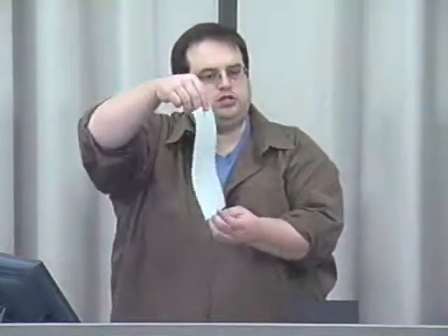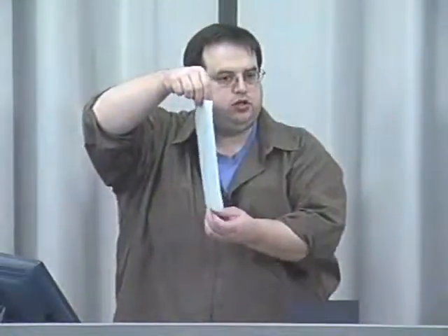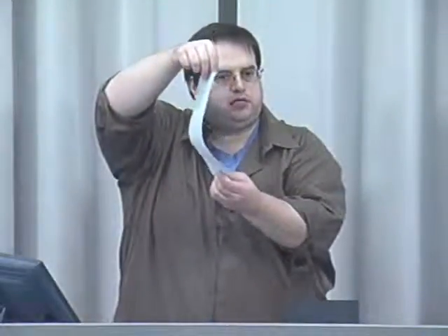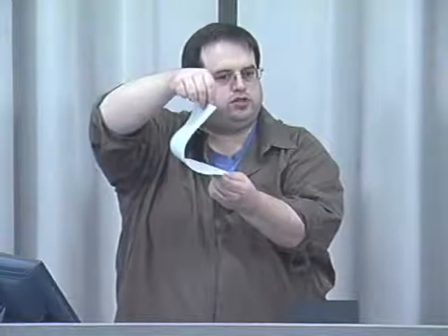When you actually do it in displacement control, you can buckle the entire system in a slow, controlled fashion. So what we're essentially doing, you're not changing the behavior at all. You're really changing what are the stops on the behavior. So you're basically slowing down the way the material is responding to a point where you can actually capture that response.